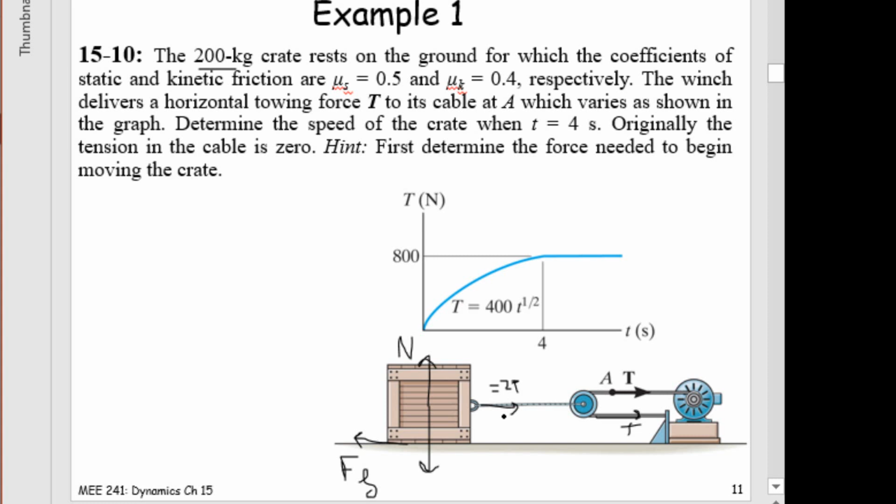All right, so this tension force should be equal to 2T because the pulley is in static. Or since the mass of the pulley is always neglected, I can take this as my free body diagram. So the crate with this pulley, and then in this case these 2T will be shown, and this force here will be internal.